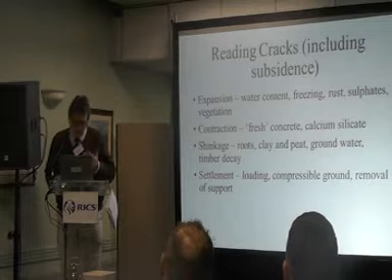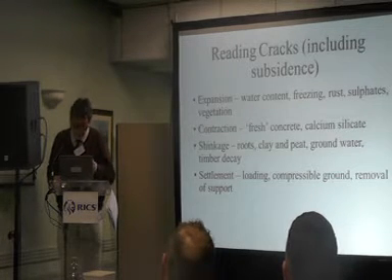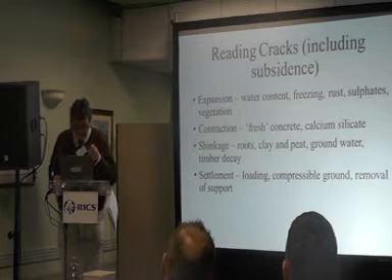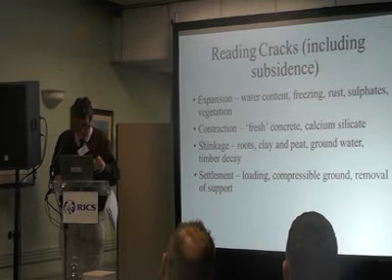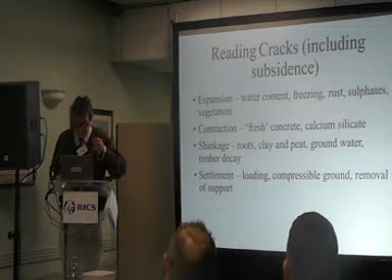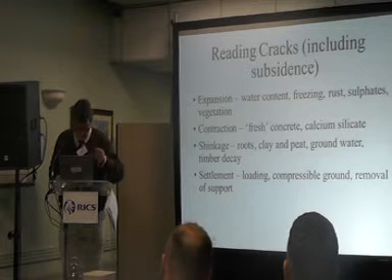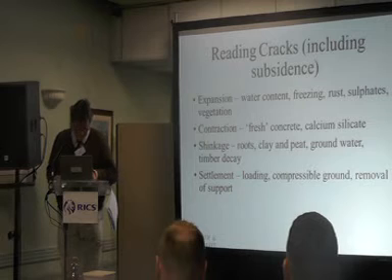Cracks, including obviously subsidence. First, just think about what's causing the crack. Is it expansion? If so, it might be water content, might be freezing, might be rust. Amazingly, iron, when it oxidizes, takes up 7 times the volume that it did before. It's awesome, the power of a rusting piece of metal.